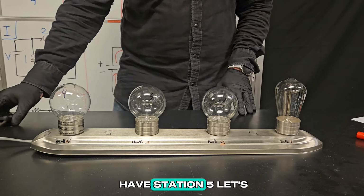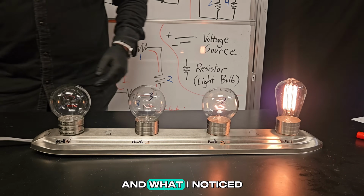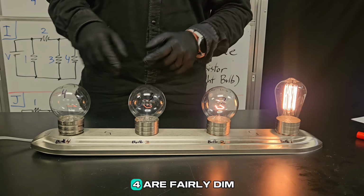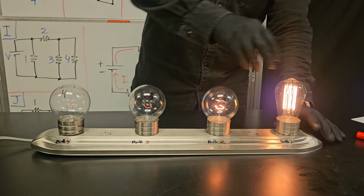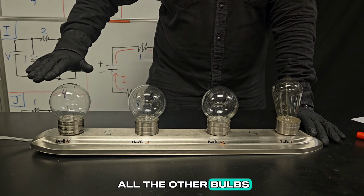Okay, so here we have station 5. Let's go ahead and turn it on. And what I notice is bulbs 1 and 2 are a little bit brighter and bulbs 3 and 4 are fairly dim in comparison. That might be a clue as to what is coming. Now I'm going to unscrew bulb 1 first, and it looks like all the other bulbs went out with it.